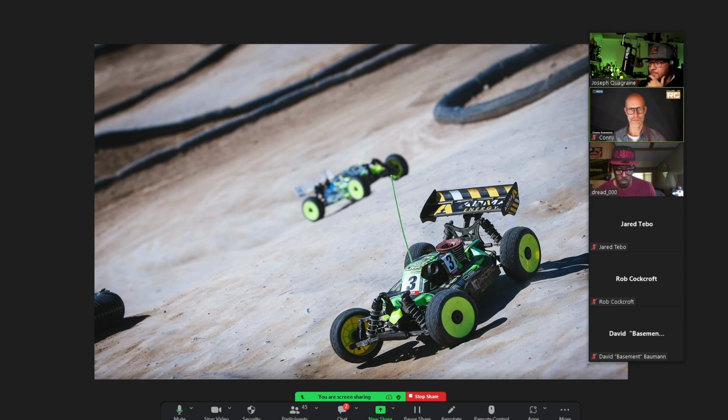The only way to reduce the amount of load transfer is actually either lowering the center of gravity or making the car wider or longer. Those things will help to limit load transfer, but the suspension doesn't do that. This is something that I often hear said, but it's not how it works. What the suspension movement actually does is it delays load transfer.